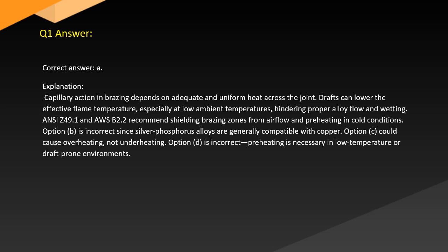Option B is incorrect since silver phosphorus alloys are generally compatible with copper. Option C could cause overheating, not underheating. Option D is incorrect. Preheating is necessary in low temperature or draft-prone environments.